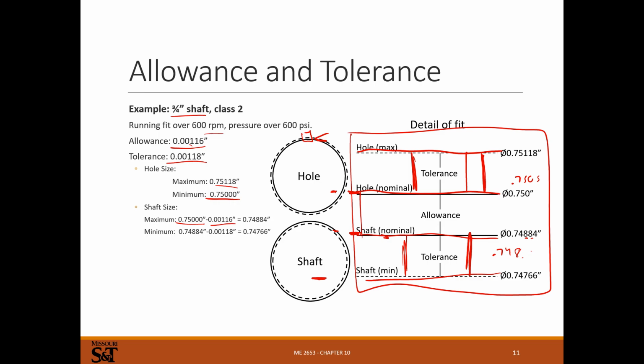And that'd give me about 2.5 thousandths. We might get a little tighter than that. You're not able to hit this kind of precision, so you need to pick something to shoot for if you're doing one-off. If you're doing a mass production run, you really want the average part to be right in the middle of this. Then you've got your normal distribution, and you want the mean of that to be in the center, and your processes need to be precise enough that they can be within the tolerance range here.